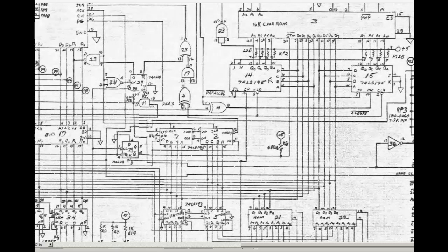So a very clever system. They've made a lot of use of a few components to get a very powerful, very fast and very flexible system where they can get data either from the character generator ROM or from the RAM or from the Nano processor. The inversion of data coming out of the Nano processor also has other impacts, of course.